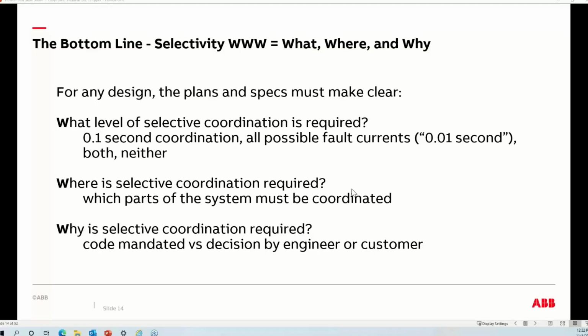Well, you could go to the panel schedules and discern the type of loads to figure out what's what, or you could call the engineer. So in my opinion, it's simply better to use N for normal, E for emergency, ATS-LS, ATS-LRS. That will more readily identify which parts of the systems require the selective coordination. So that and knowledge of the code should produce an accurate bill of material.